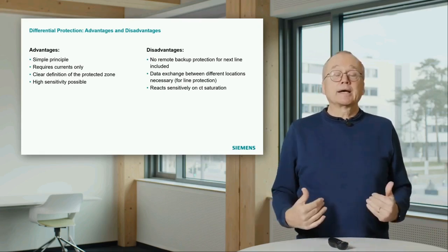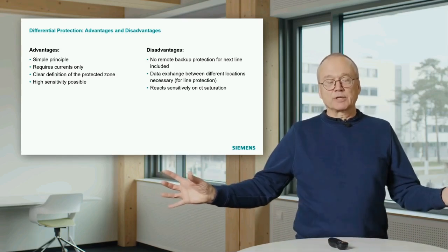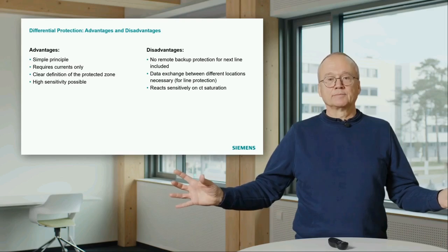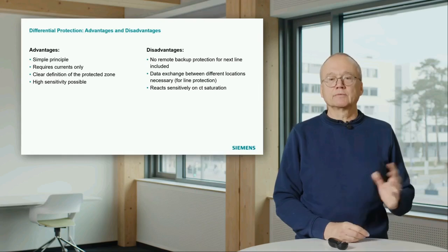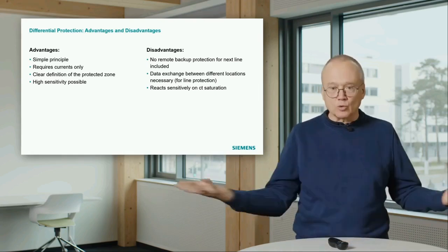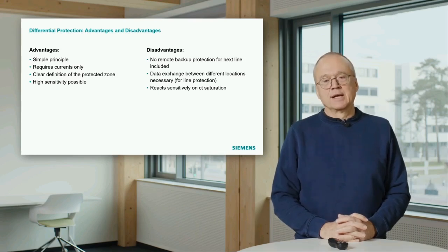Then if we apply differential protection to lines, then we need a data exchange between the two ends of the line. And this data exchange, imagine if you have a long line, 100 kilometers, you need a reliable data exchange between the two locations.